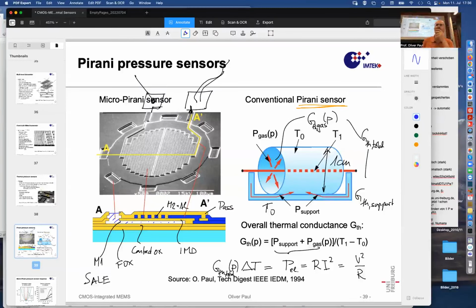Do you see that? This whole circular plate is held in place at these points, along these line segments. So it's really fixed there. Now the passivation just makes a little jump because there was metal underneath. So of course there's some topography, but the metal was removed. So this is the outline of the metal that was removed, and here are the opening windows that allowed us to reach that metal, to remove that metal.